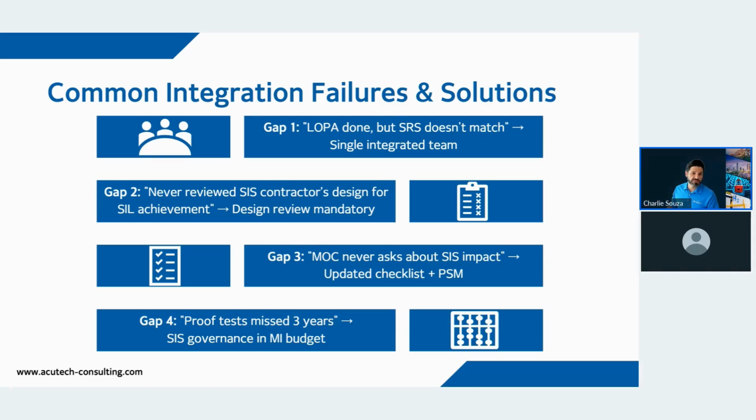Gap 2: never reviewed the SIS contractor's design for SIL achievement. Well, I have a SIS contractor, and he handles everything. He's responsible for everything. Well, again, at the end of the day, as a PSM, you know more than I do, you are the person responsible for it. You must do your due diligence to audit that contractor, make sure that the contractor is certified, and make sure that their calculations are up to par.